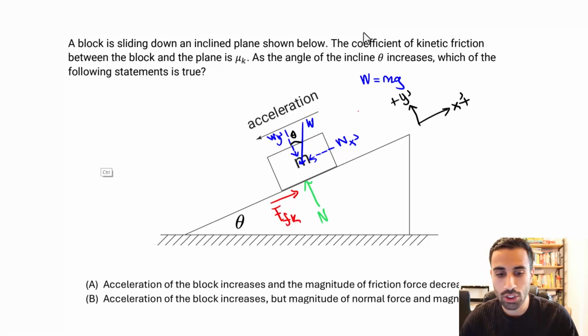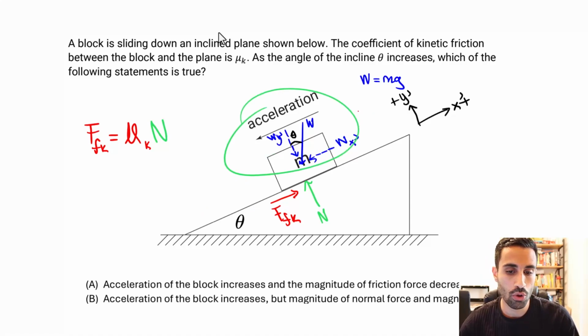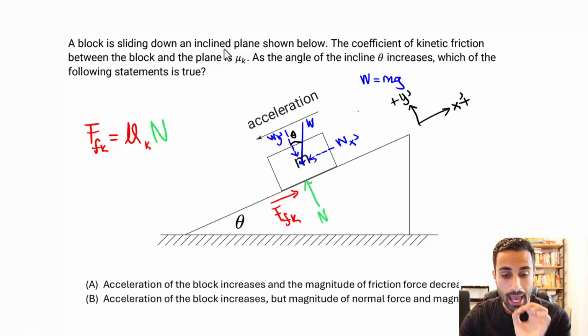And that friction force kinetic, let's write that on the side, is going to be mu kinetic, the coefficient of kinetic friction, times the normal force. That's always the formula in the state of dynamics. Things are moving, so it should go up, opposing the direction of motion or acceleration down. And that looks like a complete free body diagram.